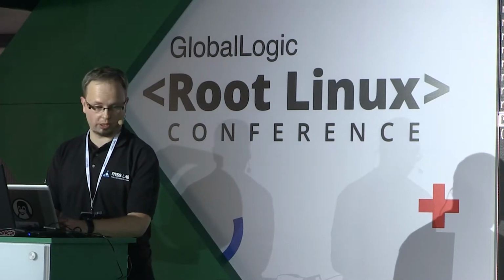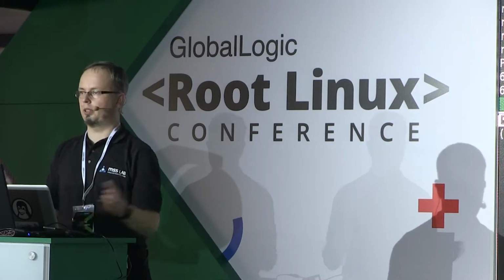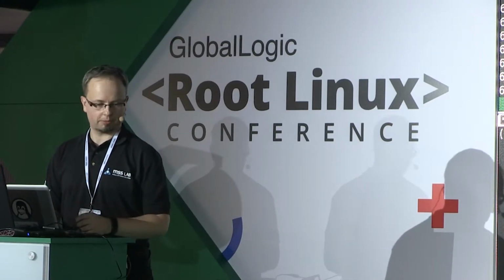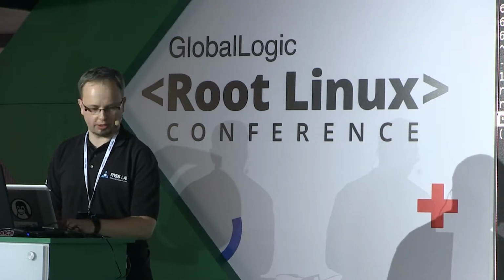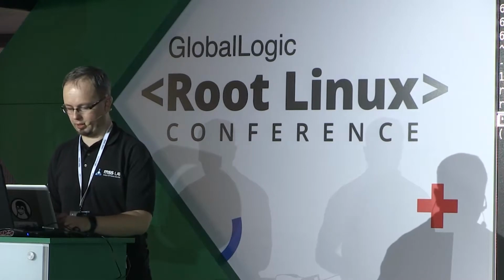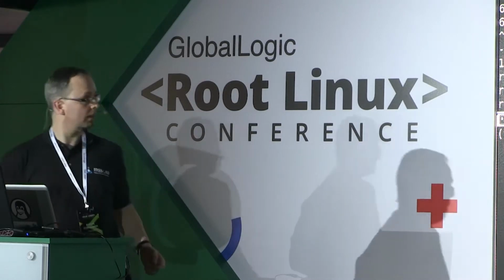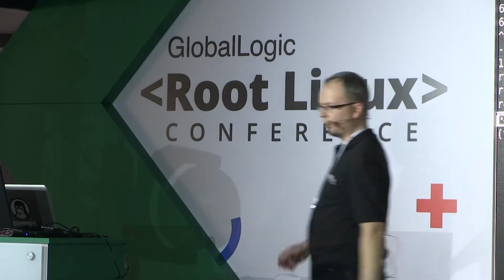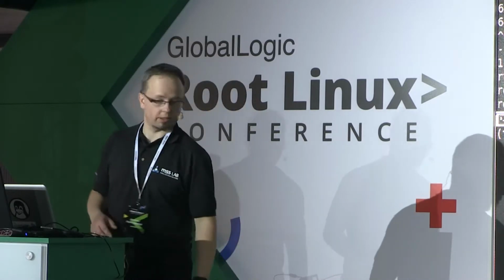Let's try the ping the other way around. Okay. So the port is not connected with an Ethernet cable to the host, and yet we are able to ping each other. Alright, so let me stop it and let me unbind the gadget from the UDC. We do it by writing an empty value to the UDC attribute. You can see that the host has noticed that the device has disconnected. And to remove the gadget structure completely from memory, you need to remove all the symbolic links and all the directories you created so far. But I won't be doing it right now.